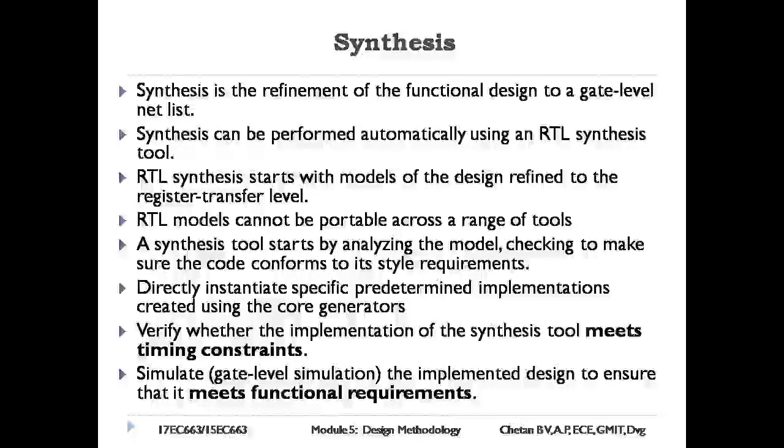RTL synthesis starts with the models of the design refined to the register transfer level. Many VHDL or Verilog features cannot be synthesized into equivalent gate-level circuits. RTL synthesis tools require that RTL models be written using a subset of language features. Example, sequential hardware should be expressed using always blocks.